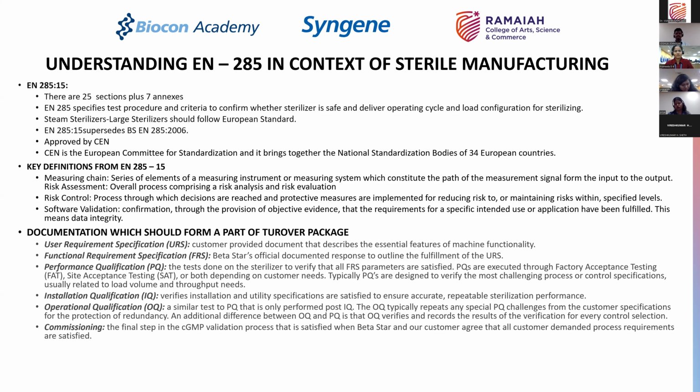After this, the equipment is shipped to your factory, to the manufacturing site for sterile products, and it is installed there. What is installation? It's a physical installation, the electromechanical installation where all electrical power is given, the UPS power is given, the control system is connected, and all the utilities, like you're supposed to give pure steam to the equipment, you're supposed to give chilled water to the equipment for rapid cooling.